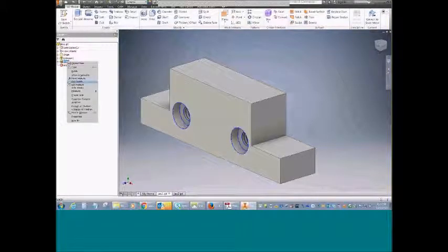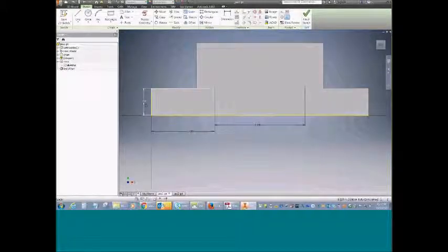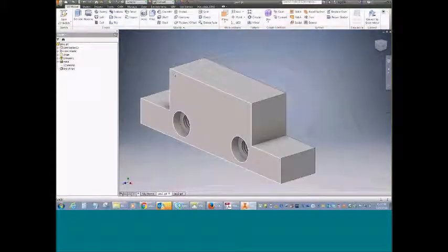I'm just running off the tree right here, but in other assemblies, we will discuss the parameters page where all your dimensions are listed as parameters and how you can export those to Excel and then interlink that Excel spreadsheet to multiple models so that if you change one dimension, they all change. Not going to do that this instant, but that is something that we do kind of play around with on one of ours. There we go. So that's all working pretty good.